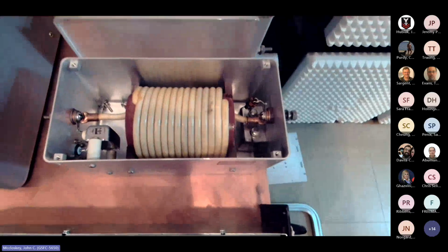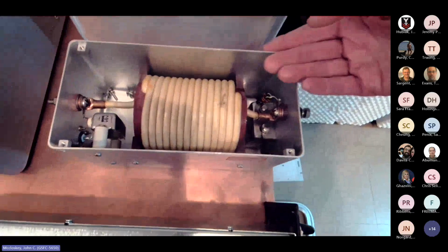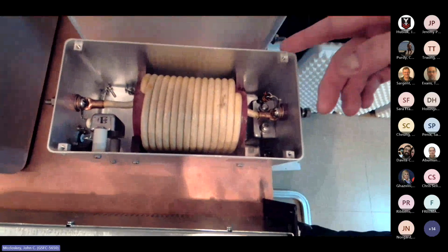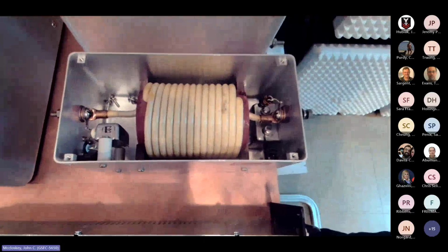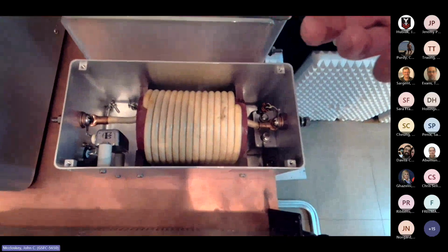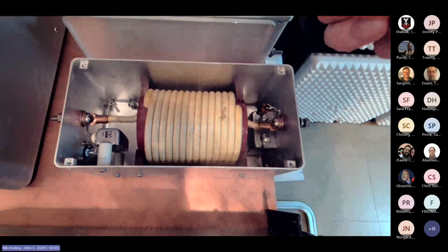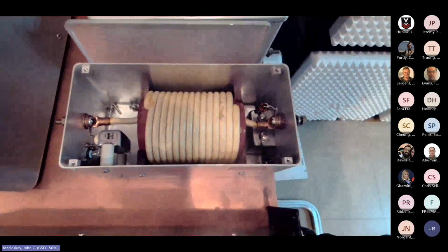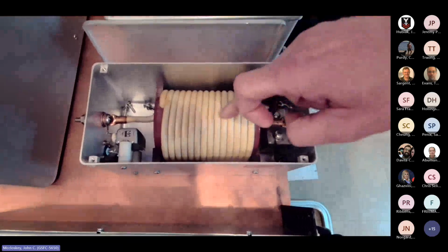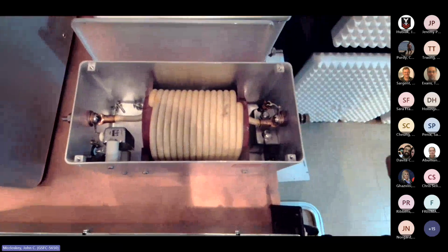So even when 5 microhenries is suggested as maybe a more realistic impedance, or the 5 microhenry LISN is a more realistic impedance for a spacecraft, yes, that is a true statement that it's more realistic than 50 microhenries, but that doesn't make it terribly realistic. It is still overkill for most of our missions.